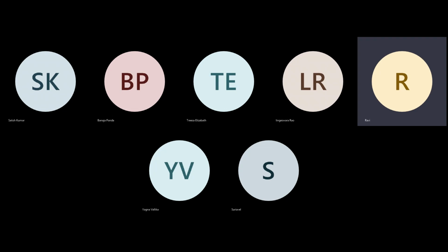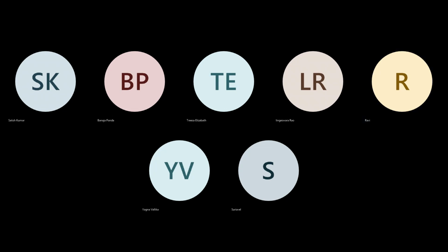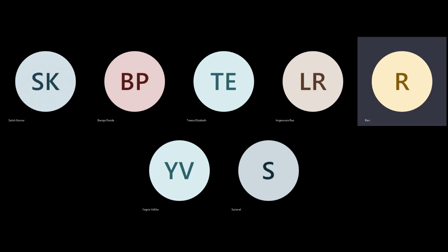So it will take the 2 cells, first push the cells into this particular placement and say, what is the route length? If I move this cell from this 1 by 2 matrix to the other 1 by 2 matrix, will my overall net length reduce or will it increase? Okay, so this is the decision making.